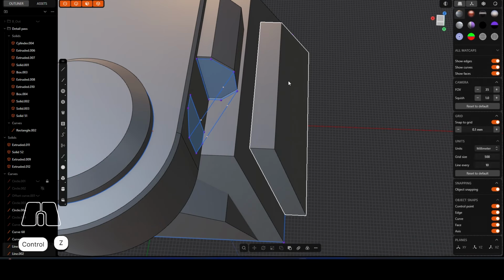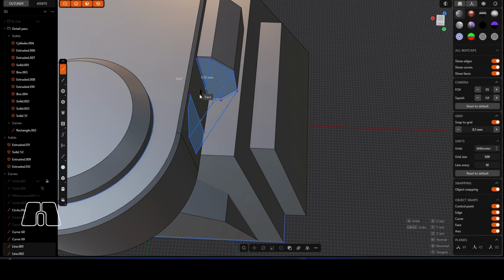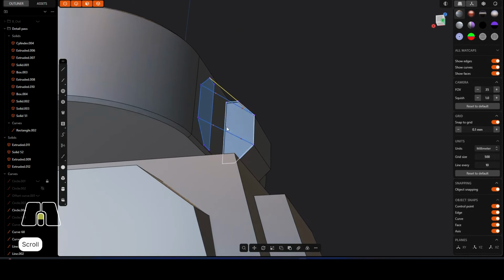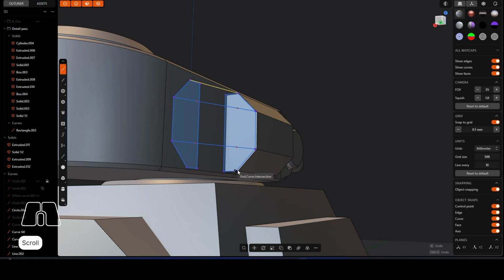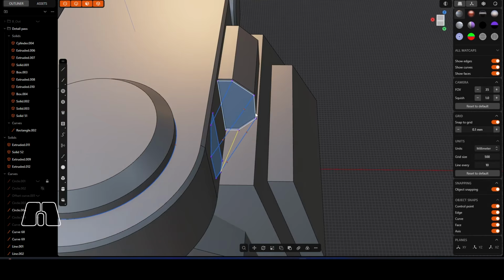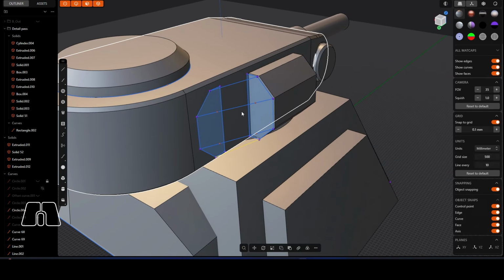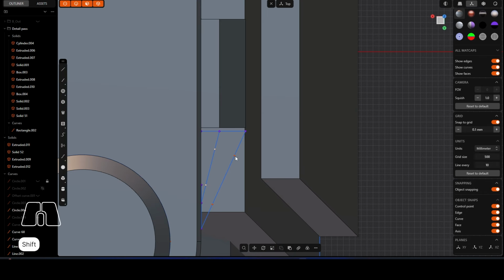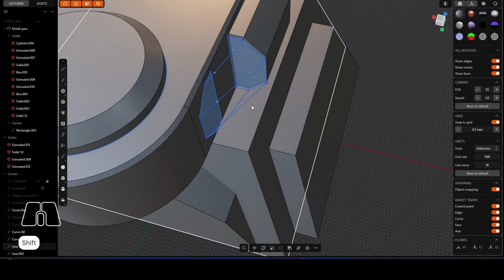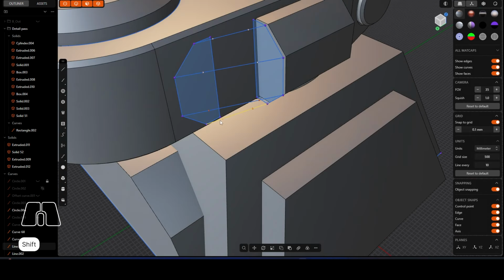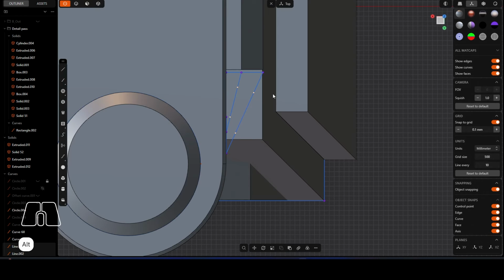Let's just go back so I can keep these aligned. We're going to loft this bit as well. So let's grab that again. So it's a really good way to make that transitionary detail from being like a hard surface area. So if we use, is it Alt S? There we go. Grab that one, Alt S. So it just allows you to make those bits of detail that you probably struggle to get in this shape, and it's one of the advantages of using Plasticity and things. Let's just make sure I'm on the correct view there.